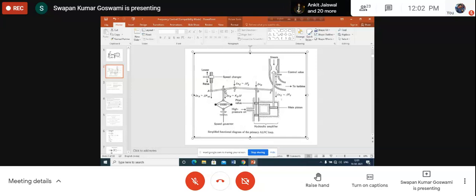If the speed is synchronous, B will be at its predetermined position. Since the speed is synchronous, the fly balls are rotating at synchronous speed. That's why B has its predetermined position. So the fly balls are rotating at a predetermined speed corresponding to synchronous speed, and there is a predefined tension on the spring because the speed is synchronous.